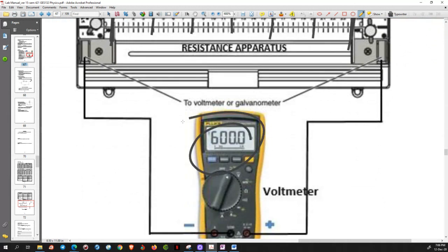So here you will get in the voltage meter. But this one is wrong. This should be in millivolt. Okay? It should be in millivolt. Why should it be in millivolt? Because the numbers are very small. And you have to press the yellow button to make it DC.